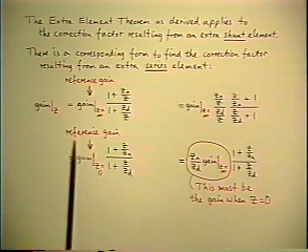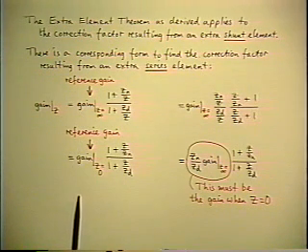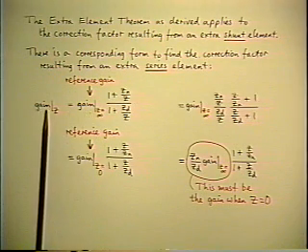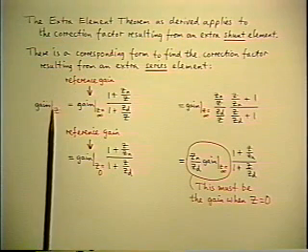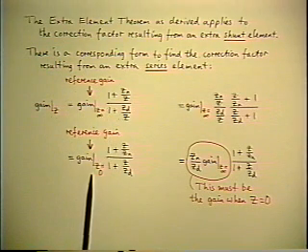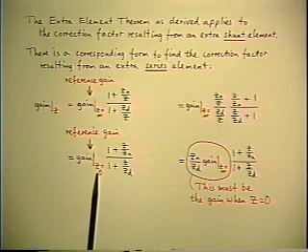So finally you can write it in this form that I've written under the other one, and that is the dual form of the theorem. It's a different choice of reference. In the original version of the theorem, you get the gain in the presence of Z in terms of the reference gain when Z is infinite. In the other form of the theorem, you get the gain in the presence of Z when the reference value of the element is 0.